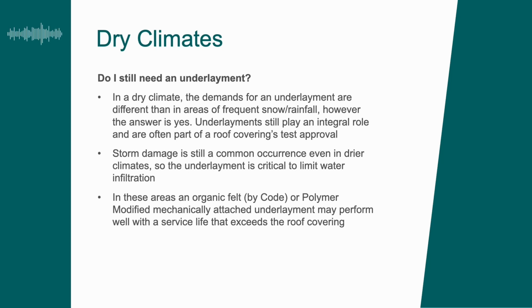There's no roof covering that doesn't require an underlayment. Now, it could be because of how the underlayment works. It's really important with concrete clay tile because they just are overlapping systems. Still important even with asphalt shingles. Even Canada finally did away with not requiring an underlayment underneath shingles. They had that for decades, and they finally realized they needed to require an underlayment underneath the shingles because they had a lot of snow issues that were drifting into attic spaces.